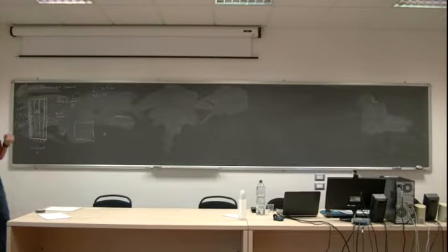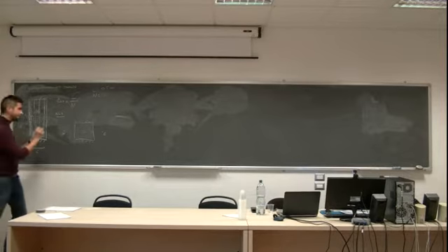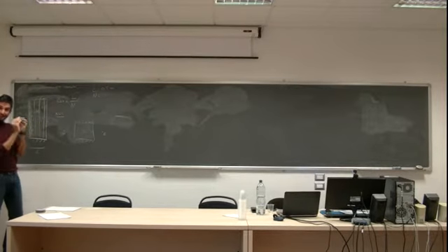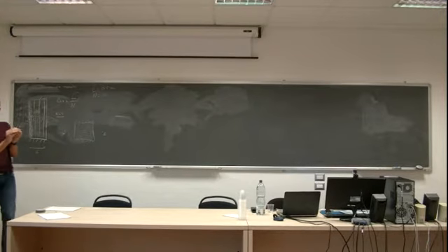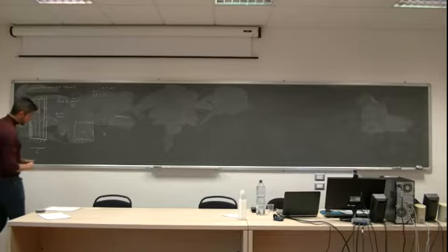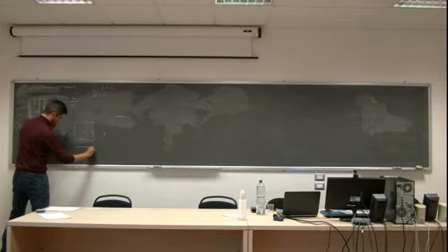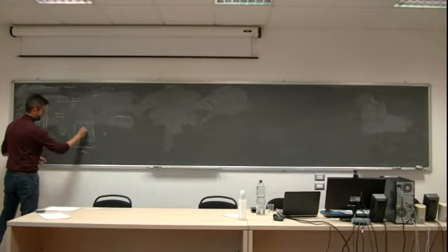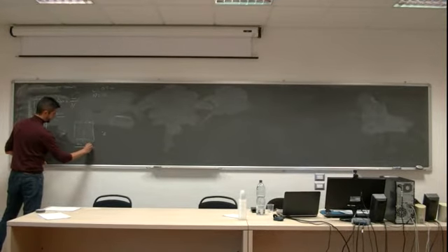And this is very important. This is why we are able to solve, because to solve the whole building wall, I'm just solving step by step the different nodes. And the temperature of each node only depends on the temperature of the neighbors. Okay? So this is delta x, right? So this is delta x half and delta x half.